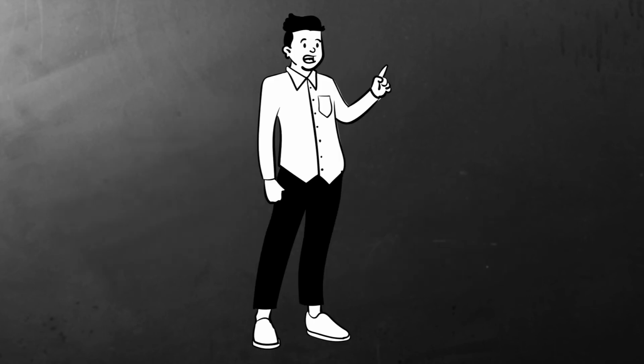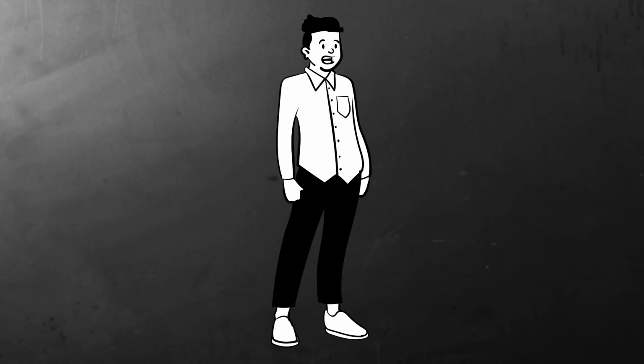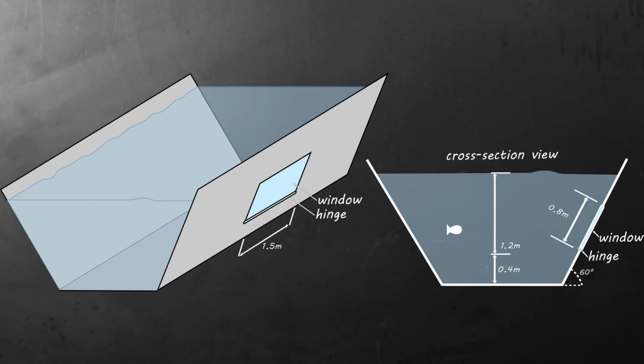By the way, when we ran through this, we never made the assumption that the wall is vertical. That equation also works if you have a window on an angle. Here's the same kind of aquarium tank, but now the wall is at an angle. But we can still define the depth of the centroid of that surface and then the perpendicular area. So the same equation works whether we have vertical walls or walls on angles.